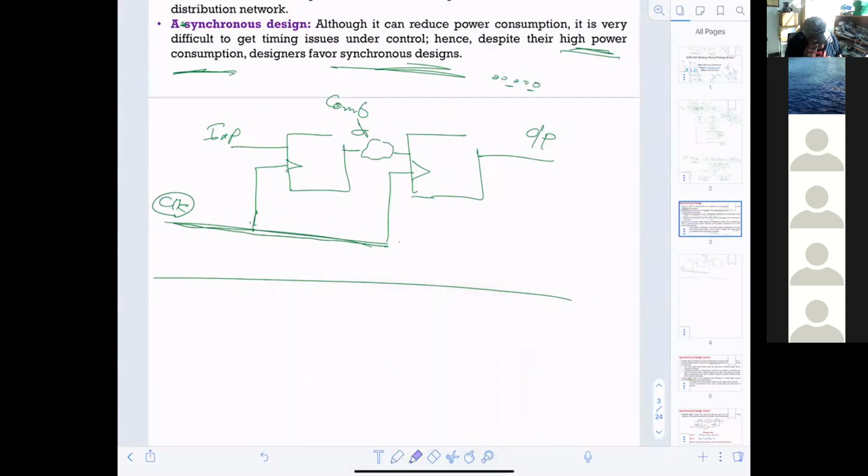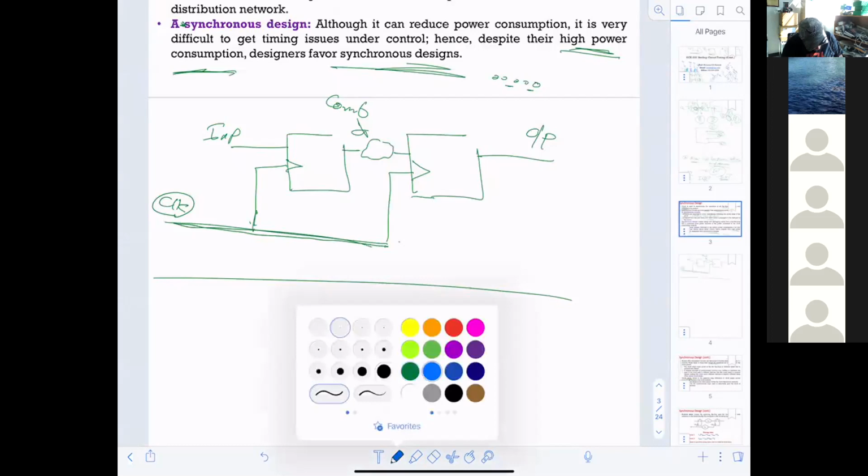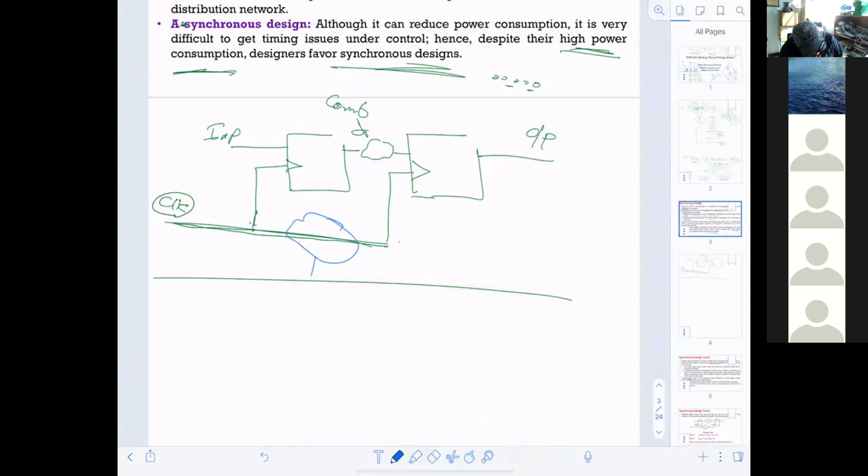Now we're gonna make some trick. What is this trick? Imagine the following. I added here a delay. So that means this one will push data, but this one will be a kind of lazy. If this is heads and tails, then the head will be processing before the tail. And in this case of synchronization, they call it positive skew.